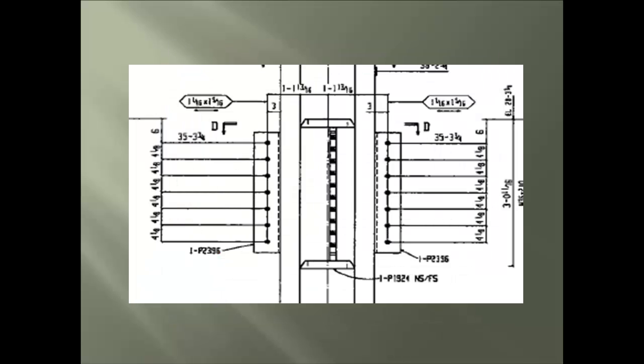Okay, here is a closer look at a section of the column elevation view. And notice for this connection plate, there is a piece mark number of P2396. So, if you were in the shop, this plate is welded to the column and would have this piece mark number written on it.